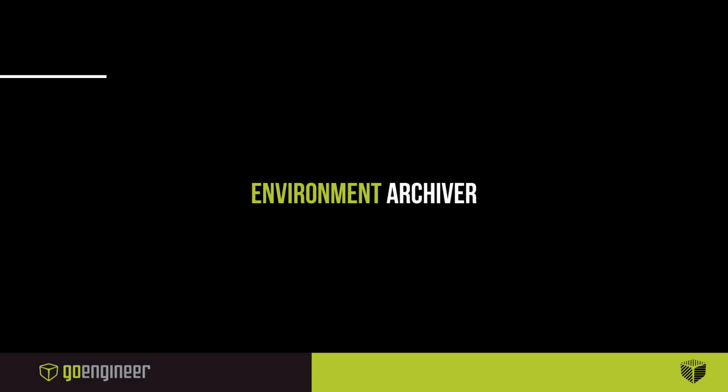Okay, so I know that people have been wanting this for a while. It's called the Environment Archiver. It is a separate executable from Electrical, in addition to archiving your environments in Electrical. What this allows you to do is back up your electrical environment, so all of your symbols, manufacturer parts, projects, everything, into a special type of zip file and store it in case you need it, or if you need to switch servers, or if you need to do anything. It's good to have them.